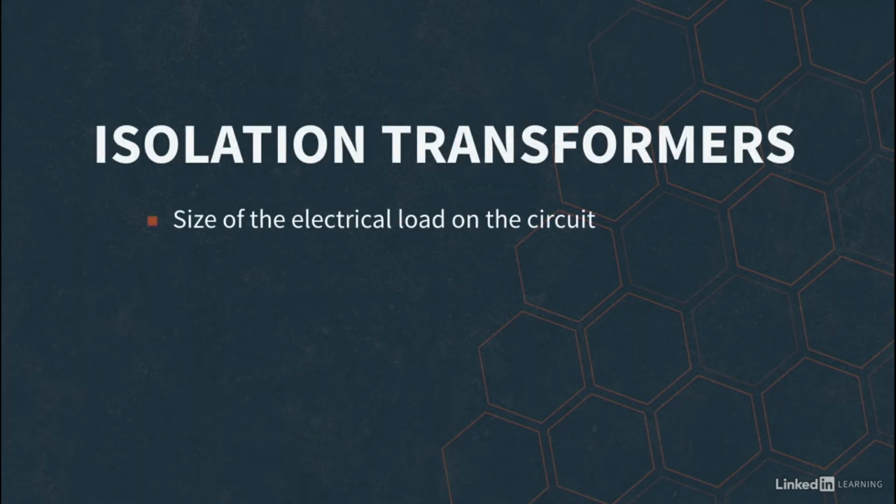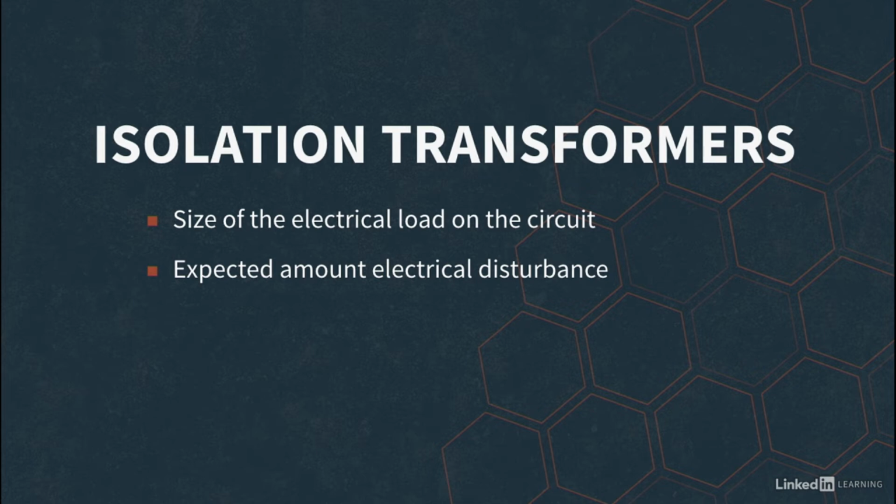Depending on the size of the load and the amount of expected electrical disturbance in a circuit, transformers can be sized appropriately to handle and mitigate these disturbances. The rating of these transformers is called a K rating factor.